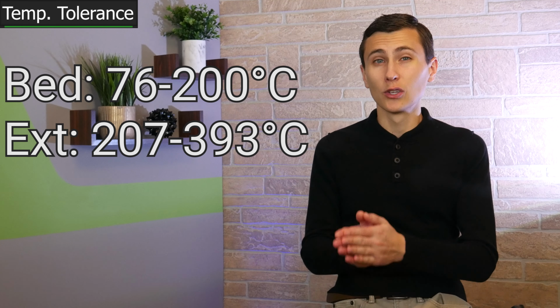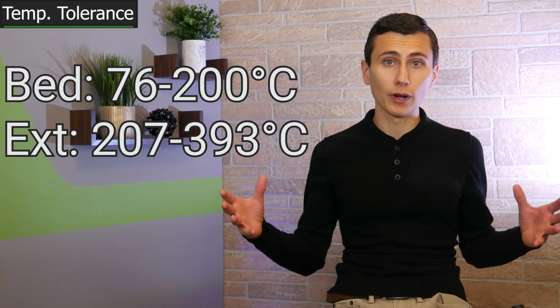The extruder temperature range varies from 207 degrees C to 393.7, so I think we've safely covered a reasonable range of operating temperatures. And if that doesn't feel right to you, if you need different temperatures, it's a single resistor swap to modify the ranges if required. It's a pretty easy system to mod, pure analog goodness. None of that digital software rubbish.